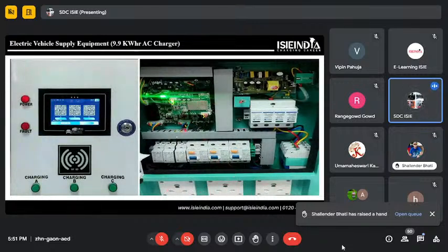Along with that, there is also a configuration and integration connection for the RFID access, and this microcontroller is suitable for running the IoT device and complete configurations. You can see that a GSM module or similar modules are also there, to connect with the server and help the operator define each of the cases. So that's the internal architecture of the complete EV charging station, the electric vehicle supply equipment system, right? That's it from my side.